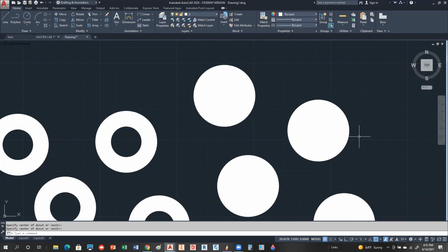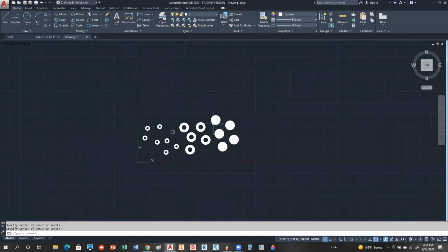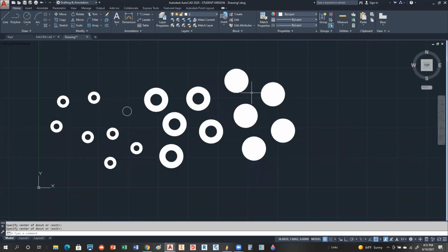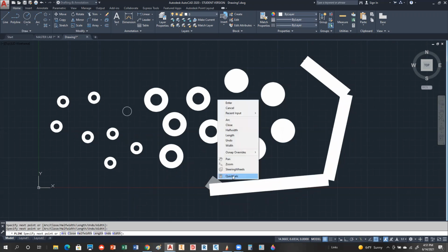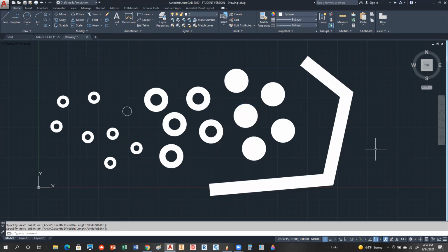So with P-lines, I want to show you this one little tool that's really neat. The way they look on the screen is governed by a command called fill, F-I-L-L, fill. I'm going to generate another P-line right here, and I want to show you when you have P-lines that have width, and let me give this guy some width. Let's make this a width of 1. Okay, so I've got a couple different types of P-lines here: donuts, filled-in circles, and just straight lines.